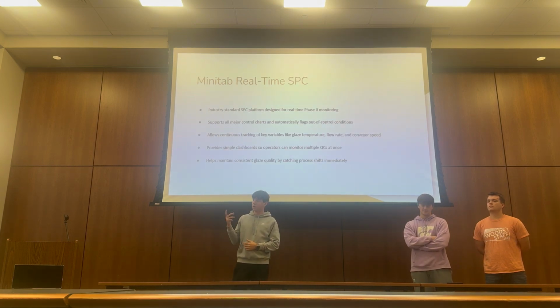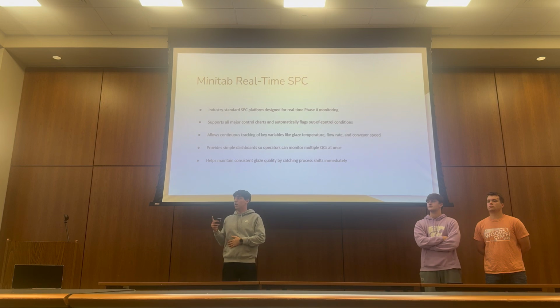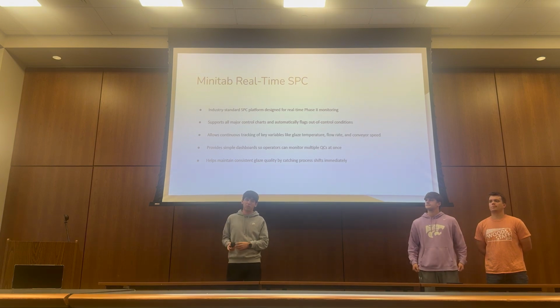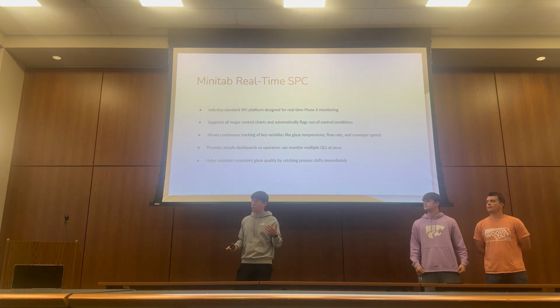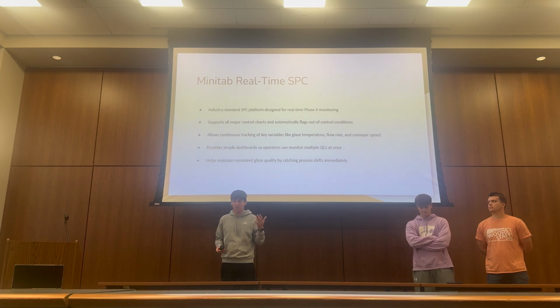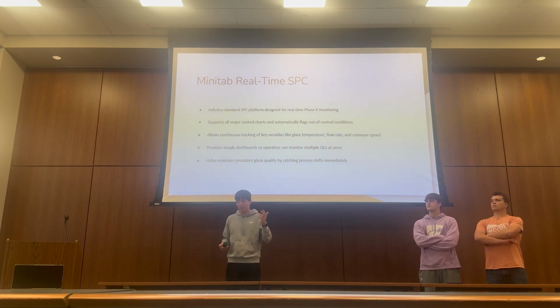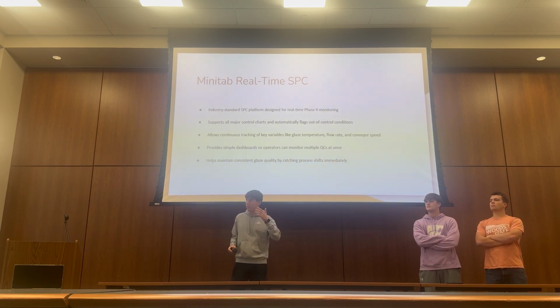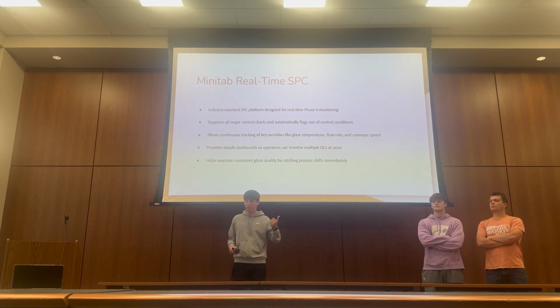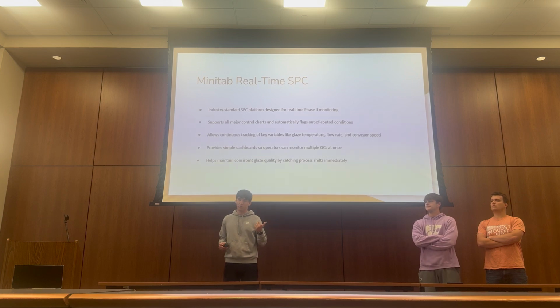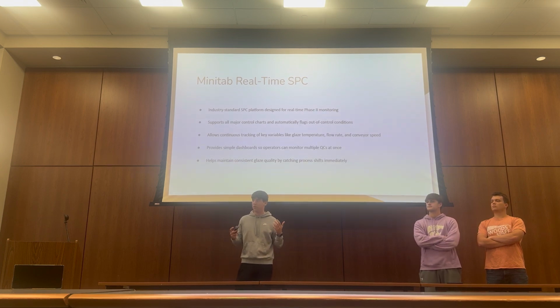And then going through with our SPC software, the one that we decided on was Minitab Real-Time SPC. The reason that we chose this one is because it is an industry standard SPC platform designed for phase 2 monitoring, so this exact situation. And it is able to support all of our major control charts. It continues to track a lot of the variables that we want. And then it does provide a simple dashboard so the operators can monitor multiple QCs at once.